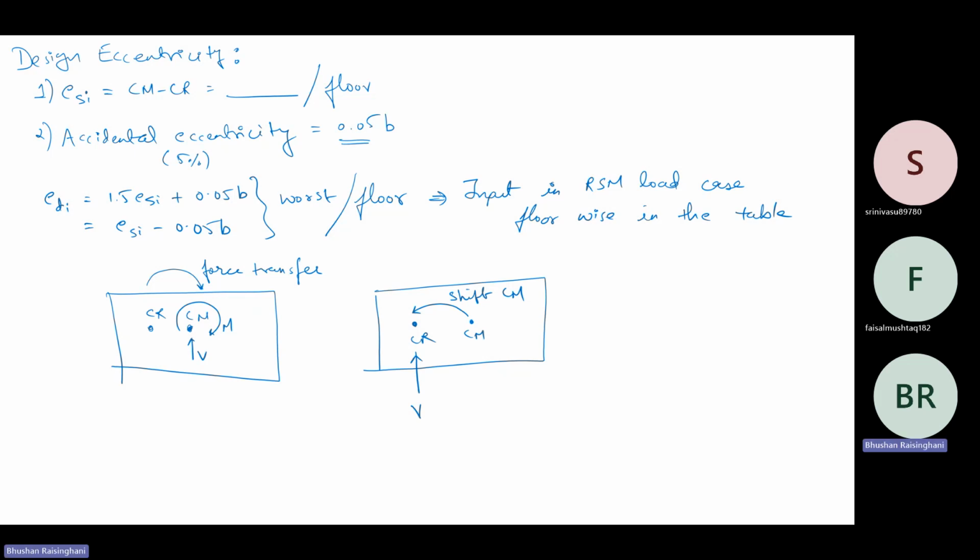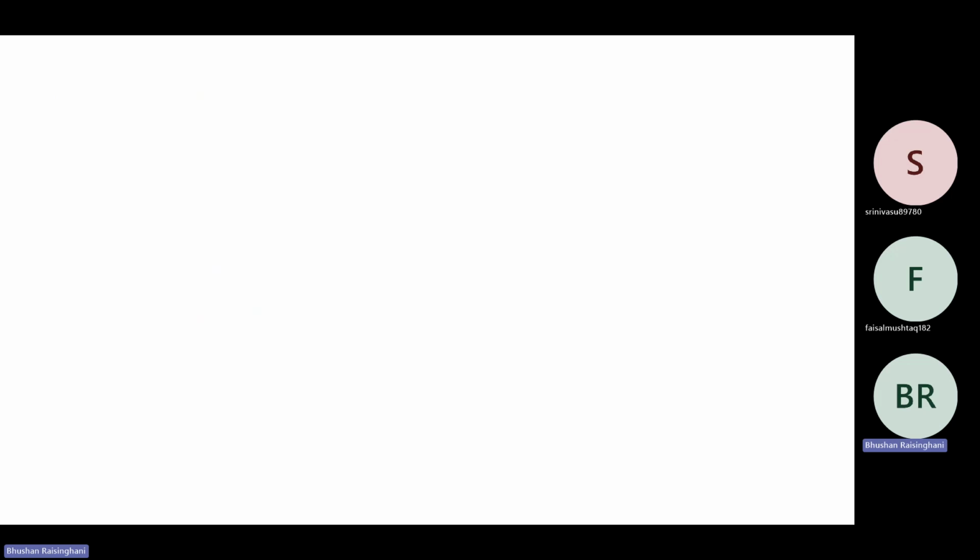So what points do we have to consider? If we list them out, okay. Always you should have a checklist initially, then it goes to your mind, and you can relate to all points. One is the plan aspect ratio, right? That is the requirement of the code as well. Then there is the diaphragm action, whether it is a rigid diaphragm or semi-rigid diaphragm.